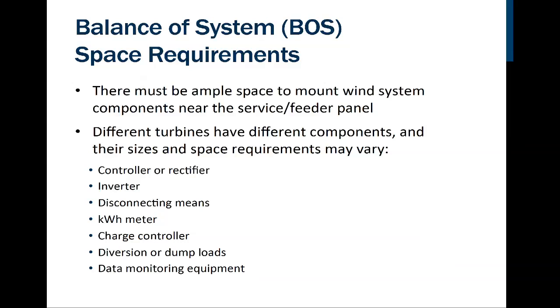We have to be able to disconnect it. There will be a kilowatt meter that is required, or in some cases you'll need a second service meter. In the event that you have batteries, you will need a charge controller because we have to charge your batteries and discharge your batteries in a very smart way. So all these things take room.